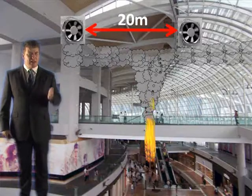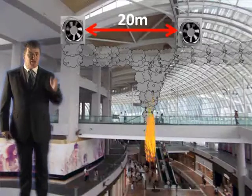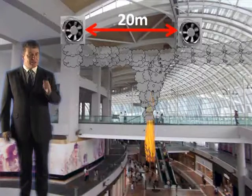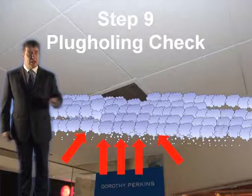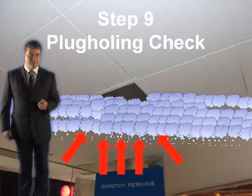Now we're going to move on to step 8, which is a stagnation check. Now remember, with mechanical ventilation, there is no requirement for stagnation, so you can go straight on to step 9. It only applies to natural ventilation. Step 9 is the plug holing check, which applies to both natural and mechanical ventilation.